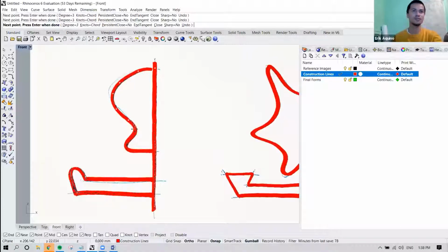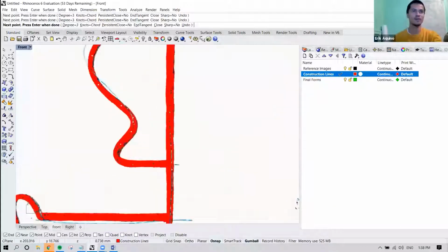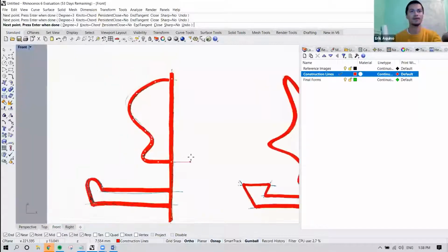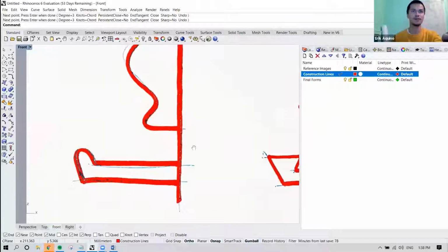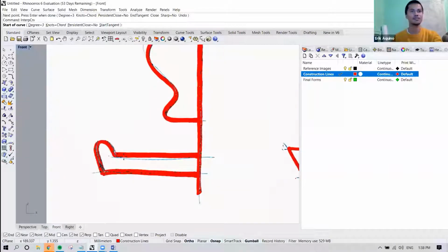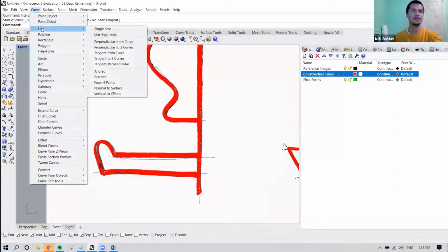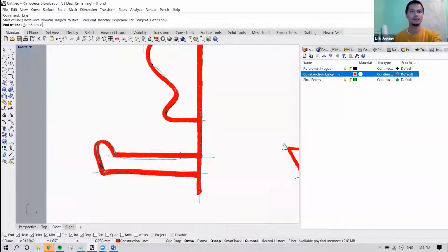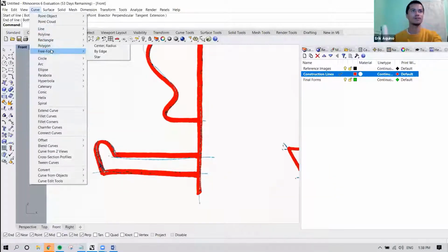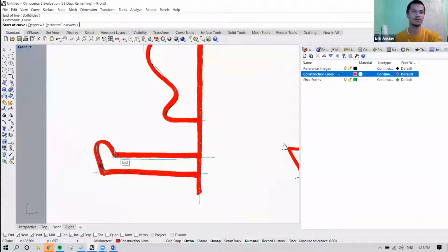Again, where there are steeper curves, you might want to have more control points, like that. Okay, and when you're done with a command or a curve, you can press Enter or space to execute it or confirm the curve. Here's a straight line, so I'll probably use a regular line segment. So there, I have another curve. I'll use a control point curve this time. It's important that we have OSNAP on and End activated so that I could find where my curve is.